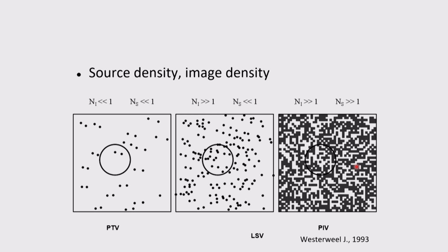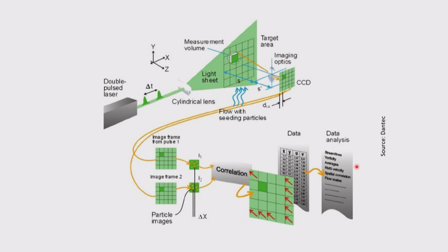So that is a PIV. Then what happens is you take two frames and create what is called an autocorrelation or a cross correlation. That means you map the intensities in the first image. I take a small area in the image, which is called the interrogation window. Let's say I have a 50 pixel by 50 pixel image, so I take a 5 pixel by 5 pixel block and try to see where this intensity pattern matches. So you can do that, right?